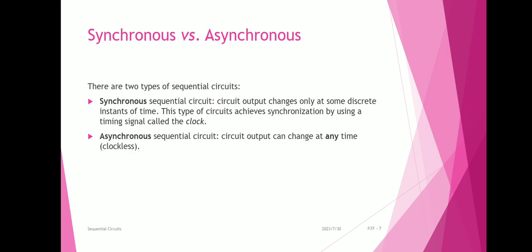Now you can see the difference between synchronous and asynchronous. Synchronous has two main disadvantages. The main one is that the possible clock rate is determined by the slowest logic path in the circuit, otherwise known as the critical path. Every logical calculation, from the simplest to the most complex, must complete in one cycle.